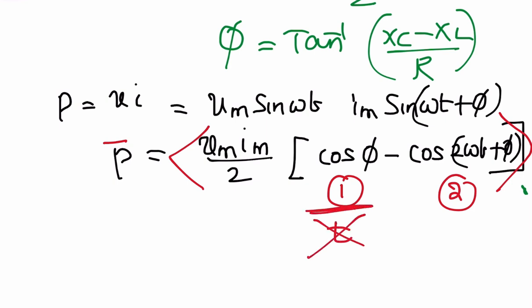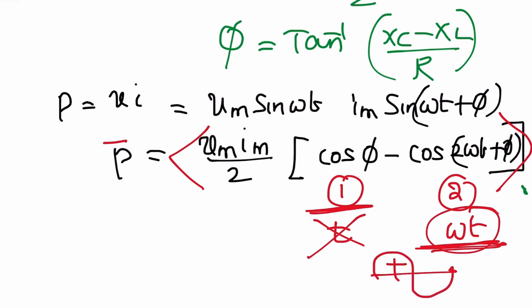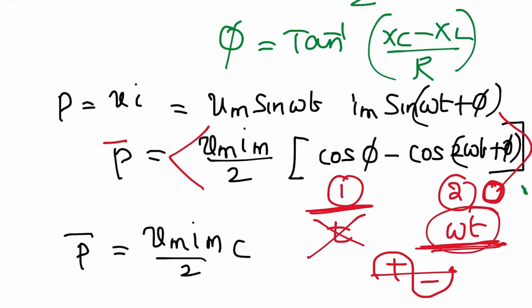Whenever there is a function of time, it varies with time, it is a cos function, half cycle positive, half cycle negative. On an average, this value becomes 0 over a full cycle. Therefore, what remains now is P bar is equal to Vm Im by 2 cos phi. So this is the power of the circuit, which is equation number 12.